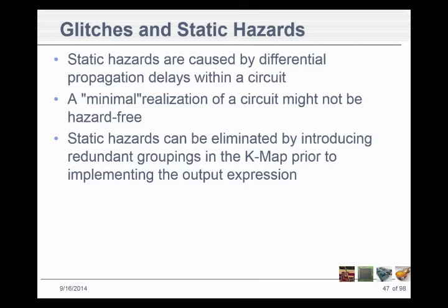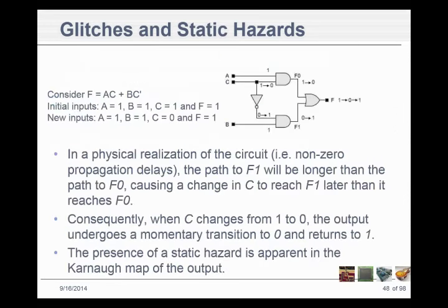What I'm talking about there is we might have gone to the simplest SOP form, but it might not be written to be glitch-free. So we've got to fix that. Static hazards can be eliminated by introducing that redundancy into the group. So here's an example. We've got this circuit.